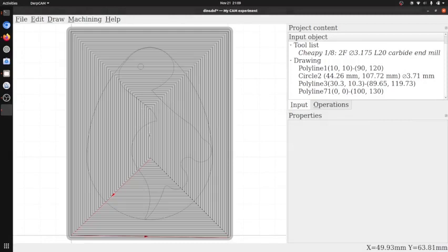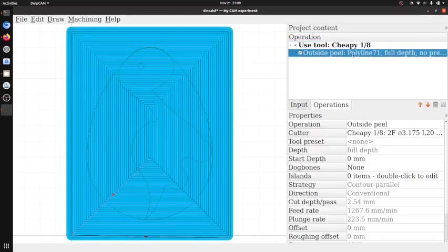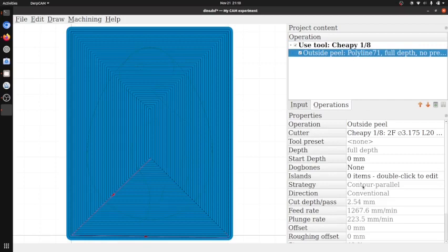Okay, so what's this doing? Let's assume that the rectangle was the edge of our material. This has just started roughing out the whole surface. We want to leave the dinosaur shape. So this is quite similar to the last operation we did. We want to change the strategy.